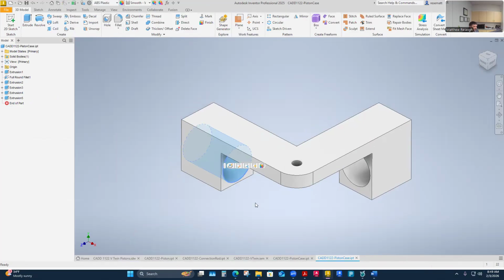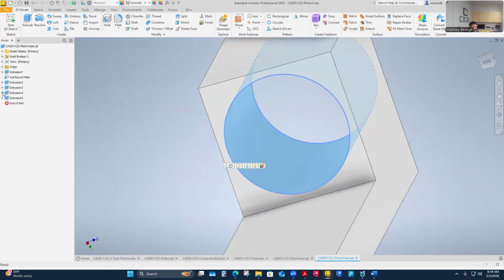So for my piston, the case bores are 15 thousandths over, so they're 0.015. It's because that longer bore, I never tried one at 10 thousandths actually. I just did one at 15. I just kind of guessed. It's got a longer bore, so I'm going to go 15 thousandths.